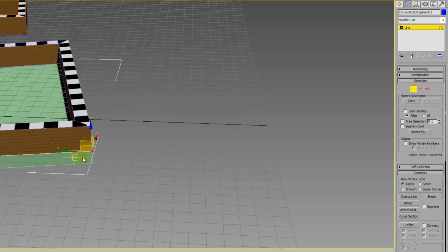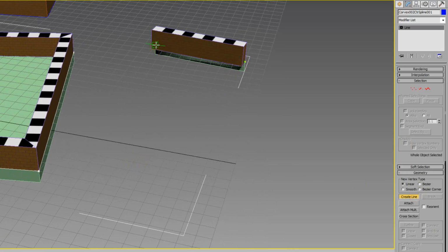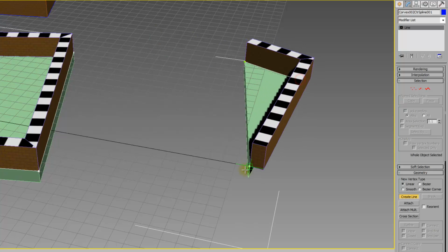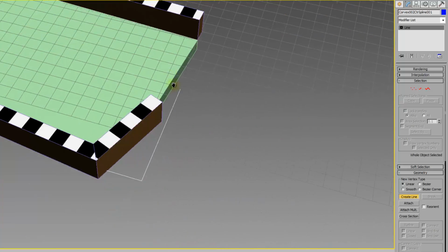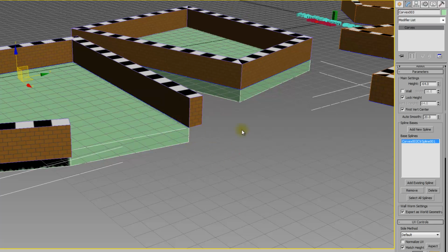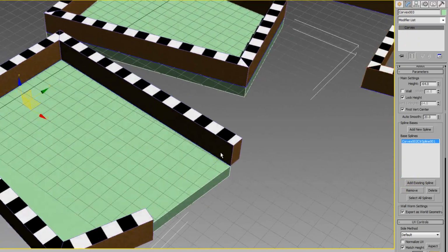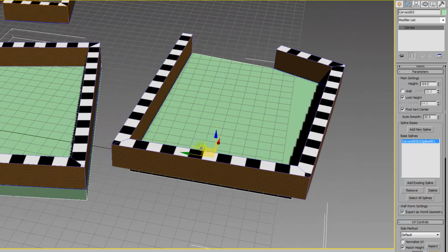And because this spline is controlling both of these, if I add any new subsplines inside of here, it will add a block and a wall at the same time. And again, because this spline is clockwise, because the ordering is a certain way, that will be on the outside. So again, the same principle applies of the ordering if I want to reverse those.